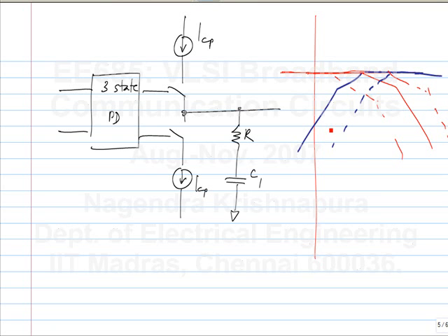Okay. And this also helps you. You have to calculate the output phase error, which gives you phase noise. We didn't get into a detailed discussion of phase noise, but while discussing frequency and phase, I had described the phase of an ideal oscillator to be an ideal ramp, and you have deviations from this. Okay. Now, just like any other noise, the RMS value of this noise is what you use to characterize the amount of noise.